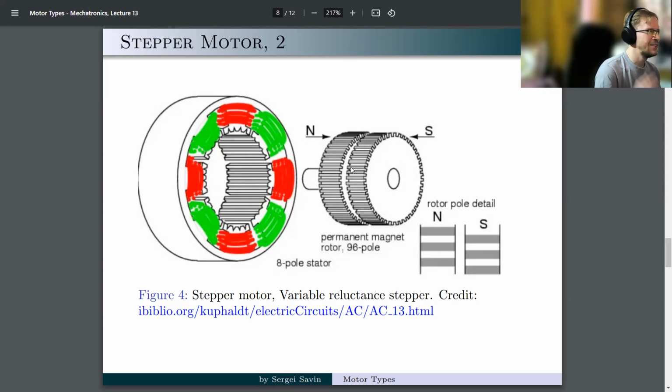To me, when I rotate a motor and I can feel the inertia going up and down as I rotate, because it passes through those different orientations of the magnet, that is when I can tell it is a stepper motor, on a visceral level, holding it in your hands. Whereas a brushless motor or AC motor will not feel like that; you can rotate the shaft and you will not feel anything. But with a stepper motor, you always feel these soft but noticeable clicks.